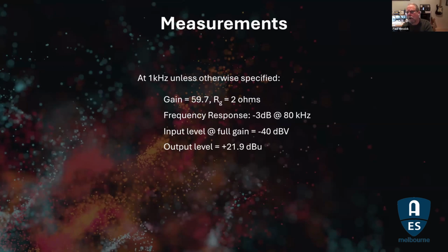But it's good to be aware that yes, there is a certain market aspect to this. And as engineers, you kind of know, I turn the filter on and off. Check it with it, check it without it. I have a nice Apogee 20 kilohertz filter that's extremely flat, and that's a pretty good standard for measuring this sort of noise. So yeah, you're absolutely right. Any other questions?